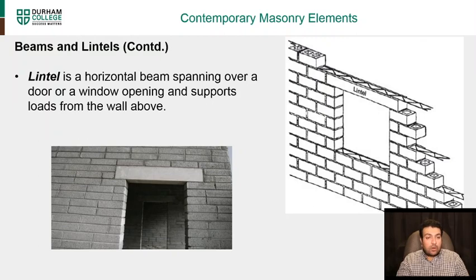You can see here a solid beam going across, then masonry units on either side. We will go into detail, but the loading on top usually goes in a rectangular format when we do the loading check on lintels. In the diagram, you'll see it comes like a triangle on top. We'll get into detail when we go into the design of lintels and beams.